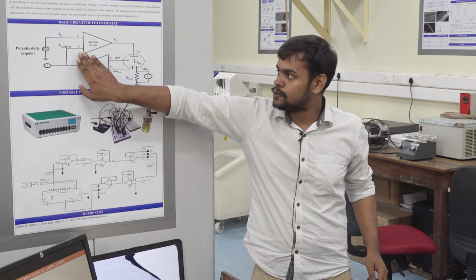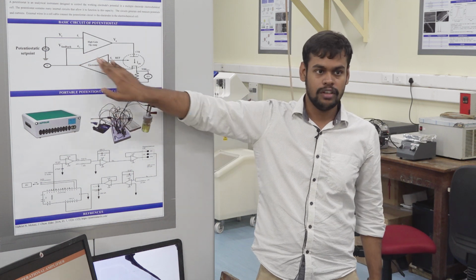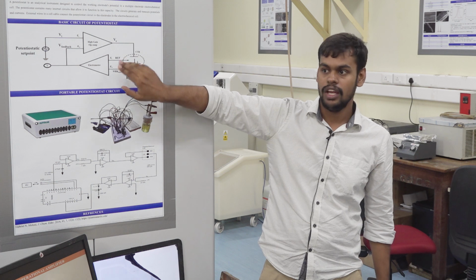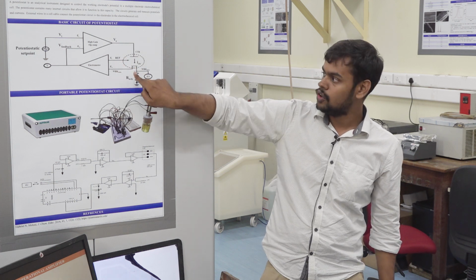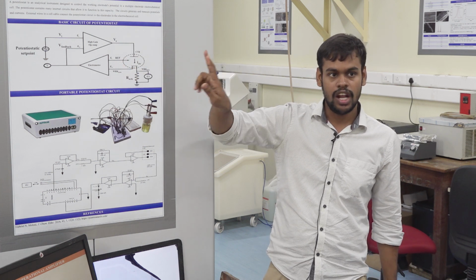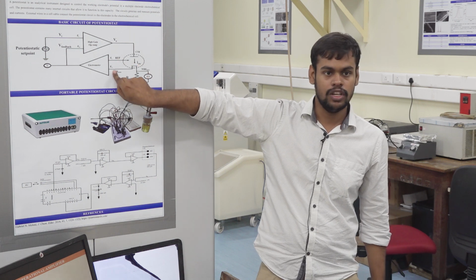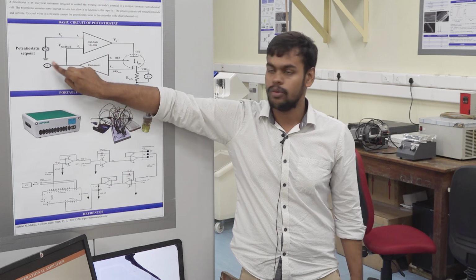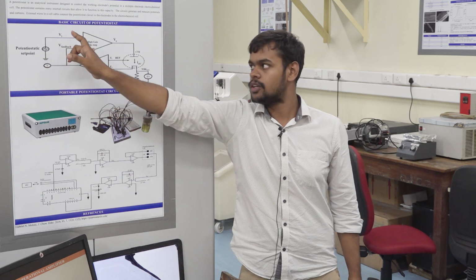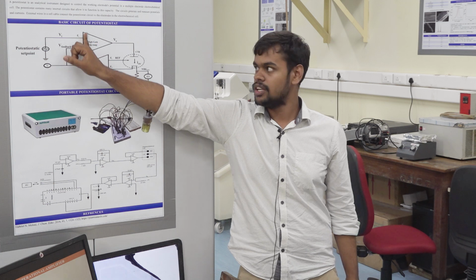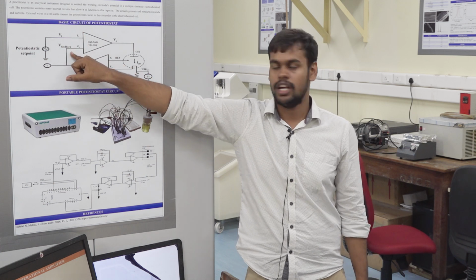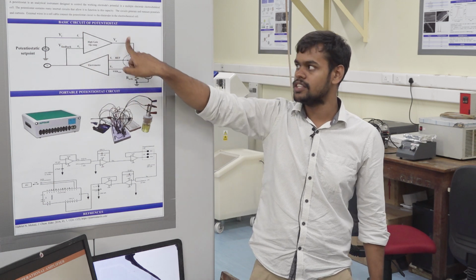Now, this full circuit of measurement with respect to the reference electrode is an electrometer circuit. It will check the potential applied on the working electrode with respect to the reference electrode. It will be measured over the electrometer and sent back to the operational amplifier. The operational amplifier will check whether both are equal. If not, it will change the value of V0.